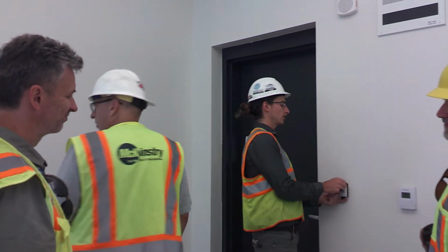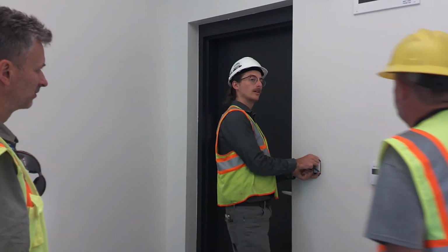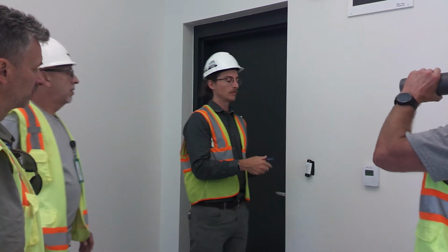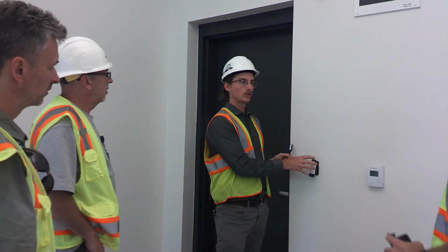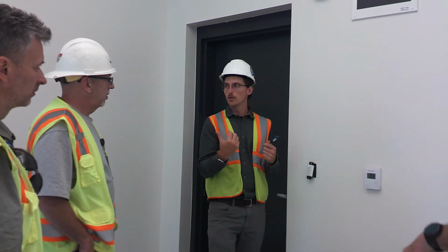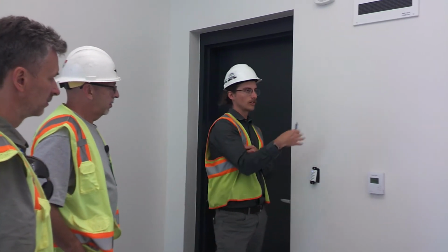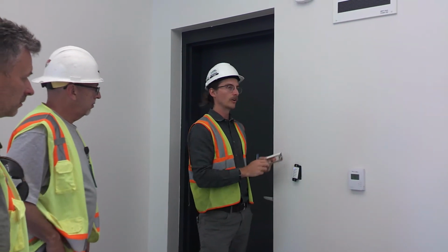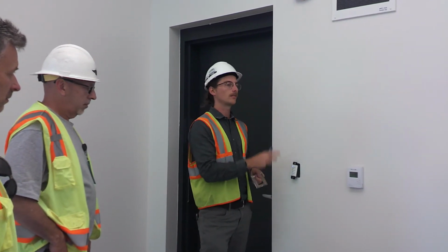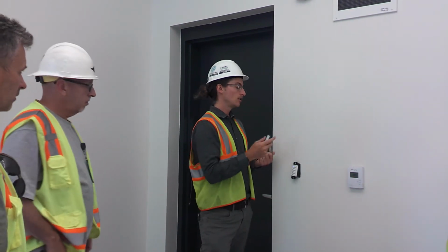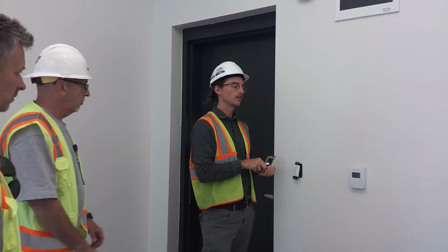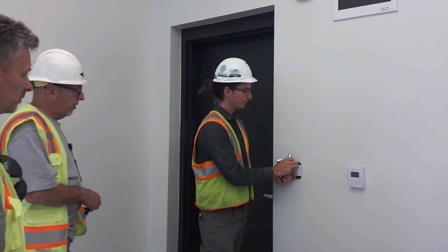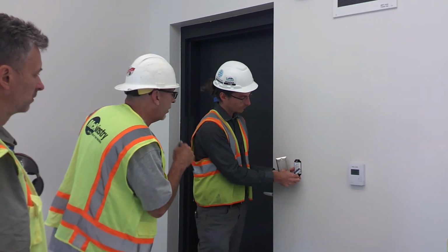Oh, actually, here's something I didn't mention about the app that's useful: you can clone the settings off of devices. So if I connect into the switch, I can clone this switch, and then if you got a new one for another classroom, that's a cookie cutter classroom, you can take that cloning and load it onto the new switch. So you don't have to worry about figuring out what the groups are and this and that. Just copy and paste it essentially. You do have to still set the area and zone, but all the other settings will copy over with that cloning feature.